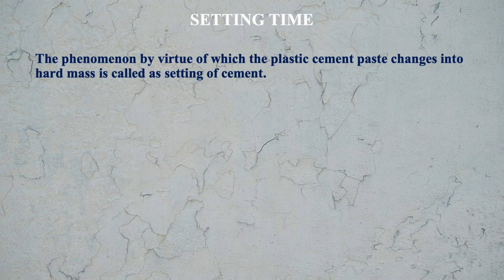Next is the setting time. What is setting time basically? The phenomenon by virtue of which the plastic cement paste changes into a hard mass is called the setting time of cement. When we add water to the cement, it turns into a plastic stage, but with time it hardens. When it loses its plasticity and becomes hard, that is called setting time.